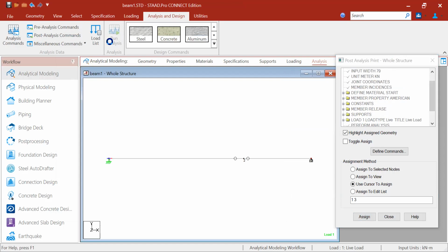After you hit Run Analysis, it takes a few seconds for the program to run, and you need to target 0 errors, and just ignore any warnings. If there are 0 errors, it means that you're good.